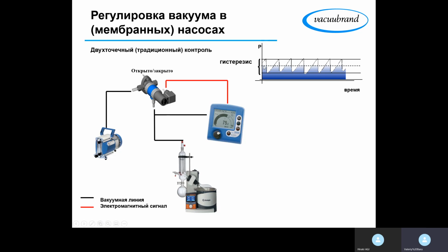So here again, here we have 75 millibar, here we will have 80, and here we have 70, right? Sorry, my mistake, I mentioned 5 millibar. We need to set a delta P of 10 millibar then, because we are reaching 70 millibar, right? So in this case, we will have the evaporation which goes from here to here, right? Because we have 75 millibar here, the substance boils, it will boil in this region.